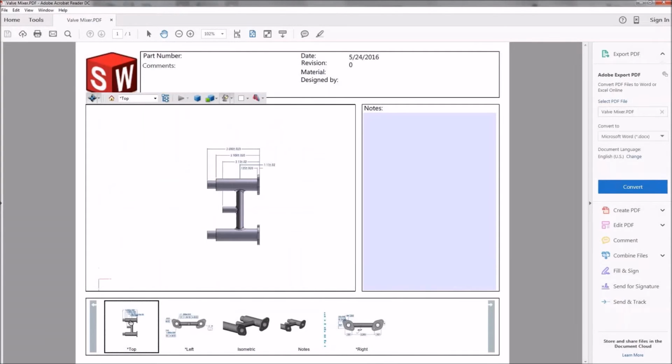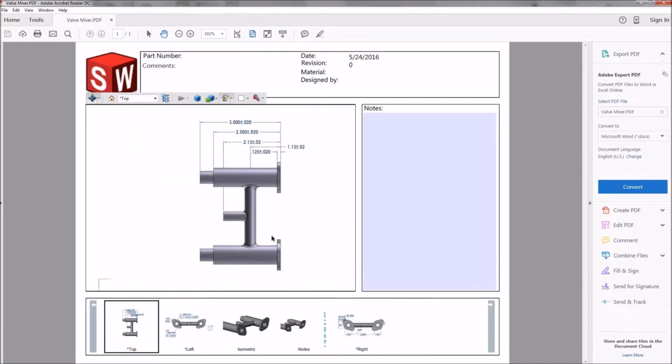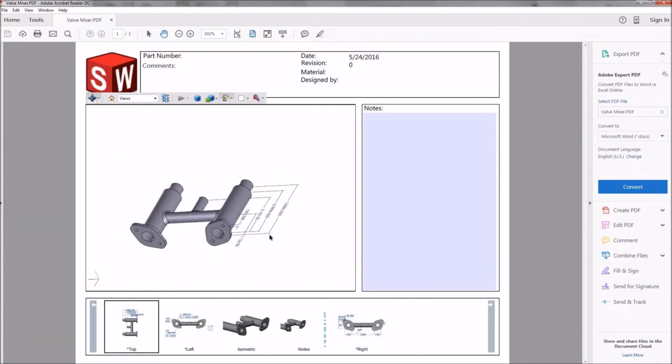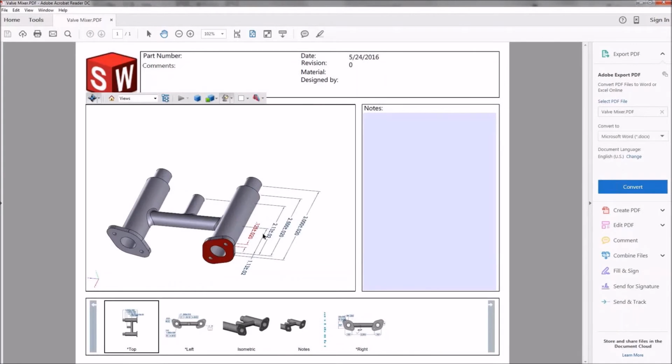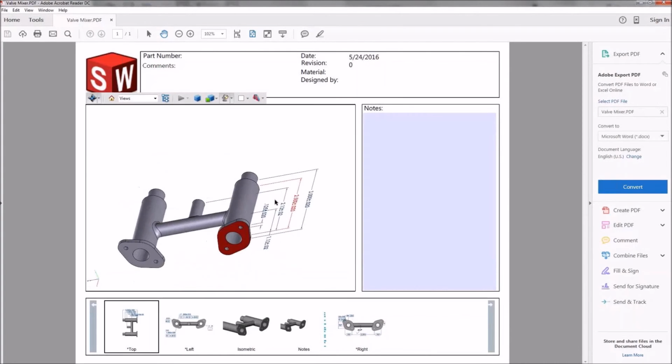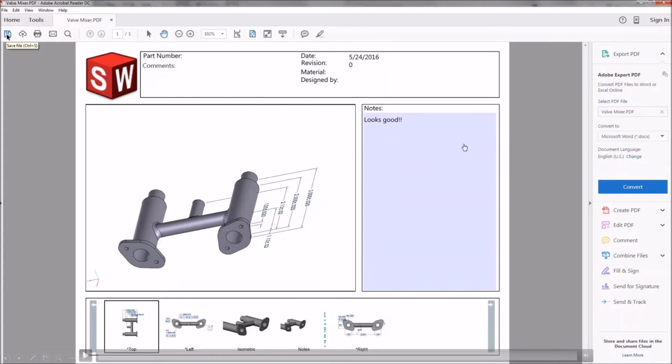So that's another layer of associativity and clarity that's available in a 3D document that's not available in a 2D printout. Again, if I rotate the faces while selecting the dimensions, I could see those highlighted faces. And we could even use a PDF like this for the approval process. So we could add areas where other viewers can add notes and so forth. They could save that PDF, and now it could be a place to contain each of those notes along the approval process if necessary.